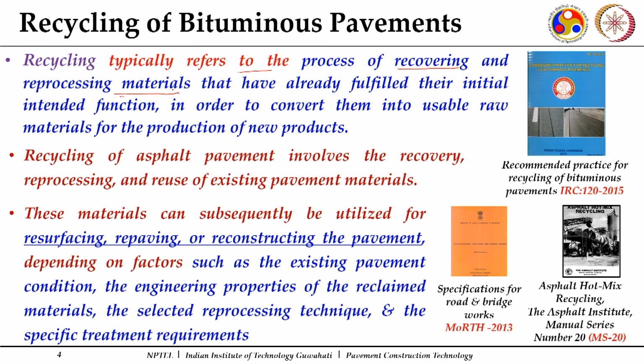Some process has to be there, and specifically what material we are going to look for. It is the materials which have already fulfilled their initial intended function. So, any layer which has already served for a number of years or has shown some premature signs of distresses and failures can be a candidate for recycling. So, recycling typically refers to the process of recovering and reprocessing materials that have already fulfilled their initial intended function in order to convert them into usable new materials for the production of new products.